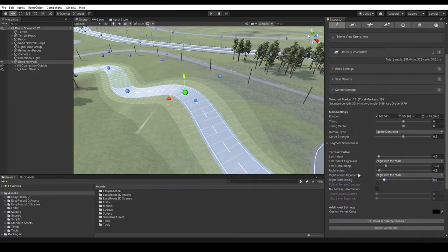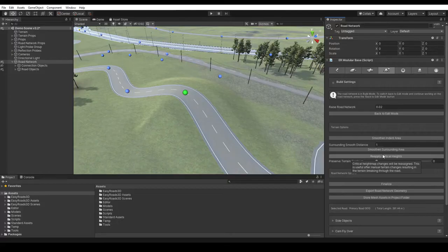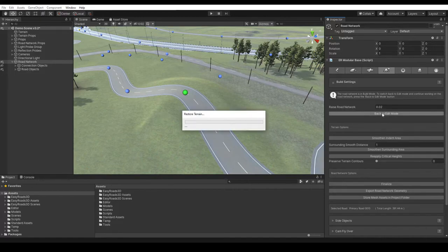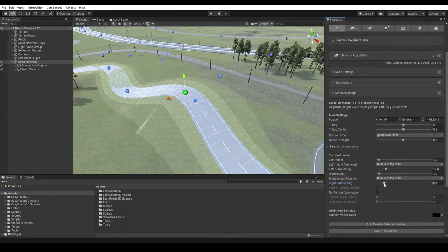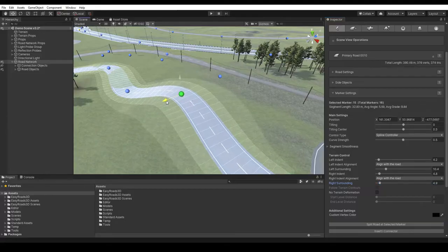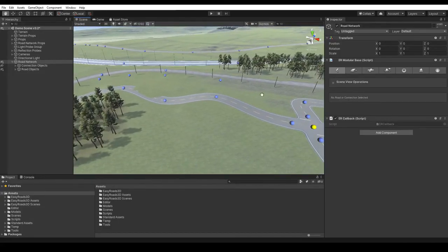There is some overlap here that may be a little bit too much. We will see. Yes, the terrain is not 100% smooth here, but we can easily fix that. We will decrease the surrounding value a little bit in edit mode. Something like this. Customizing these indent and surrounding values can, for example, also be used to flatten the terrain for buildings right next to the road, or to create parking zones in hilly areas.